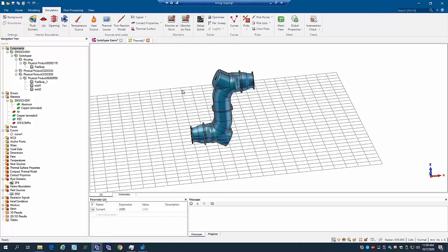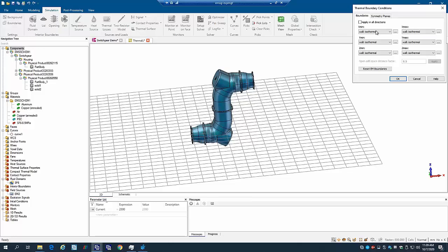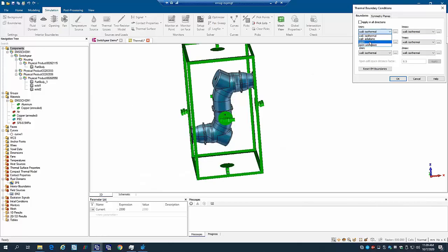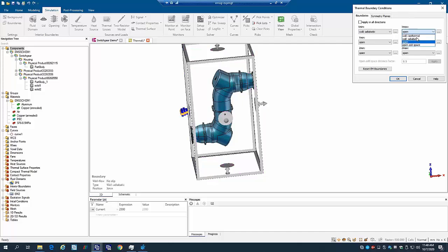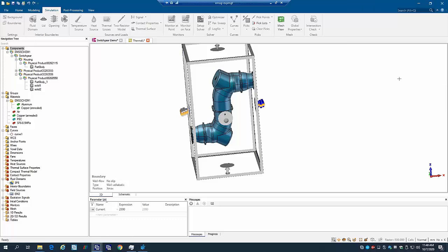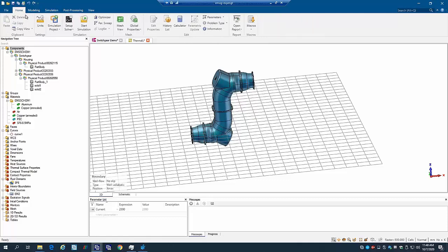And then for the boundary, by default, they're like wall. That's not good. We want to have open boundary, so the air outside this device can go in and out. And then on the two sides touching the lid, I would say adiabatic, meaning no heat transfer here, only heat transfer opening over here. Then I'm really all set here and can do a save and start solving.